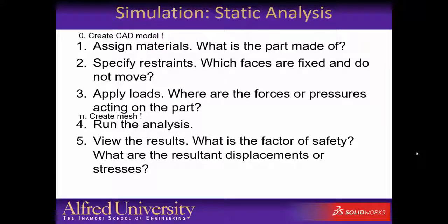Once the restraints have been defined, you can apply your loads. These can be point forces that act in a certain direction at a certain point. They can be pressures or distributed loads that act upon an entire face or line. They can include gravity, friction, heat. There are many kinds of loads. For the purposes of our demonstration and for our last project in this course, you'll be either utilizing a distributed force over a face or a gravity effect as shown in the demonstration in a moment.